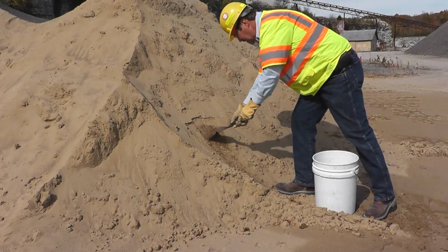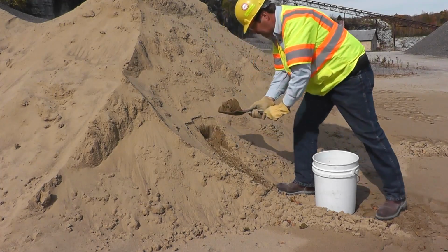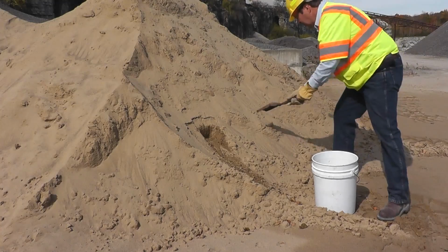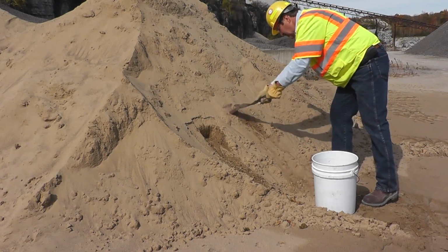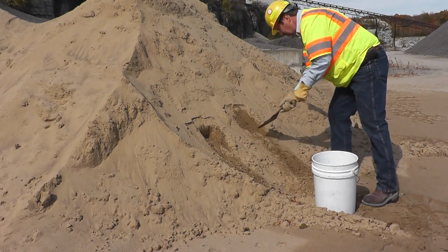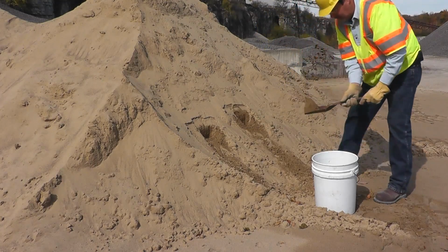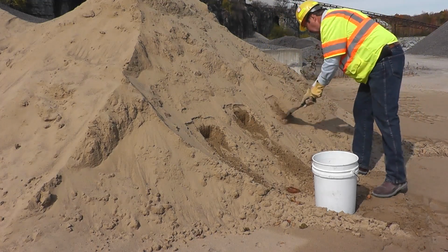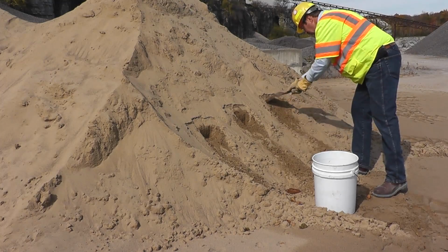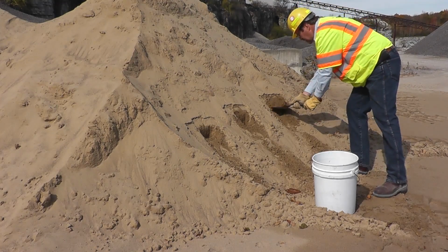In the event that a fine aggregate stockpile does not exceed the height of the technician and there is no apparent segregation, the technician may procure the sample directly from the face of the stockpile. However, before actually obtaining the sample, the technician shall first remove the surface crust from the sampling area or areas.